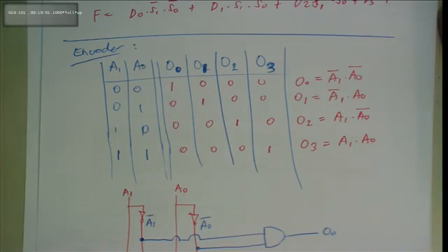Not 100, it's actually 2 to the power of 7 is 128. So the last 28, you don't connect it to any LED at all, right? The last 28, you just leave it blank, don't leave it dangling, right? Just terminate it over there, all right? And only the first 100 you're going to connect, right?